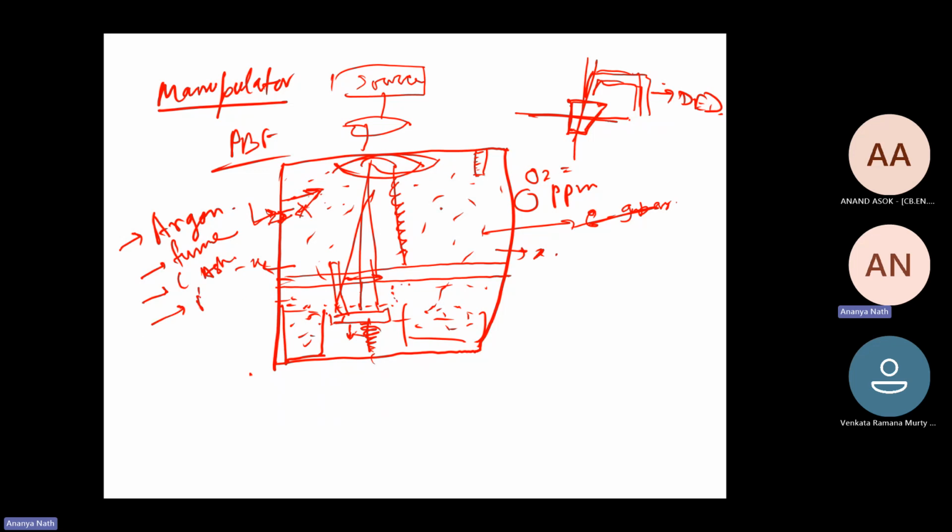Then we have the powder particles also flying here and there because they are very lightweight. So these all are now mixed in the environment inside the machine. These are not only argon, they have all the things. If there are this fume, ashes, powders present after one layer, then after 500 layers, the chamber will be filled with fume only and there will be no argon. And you cannot separate out these things very easily.